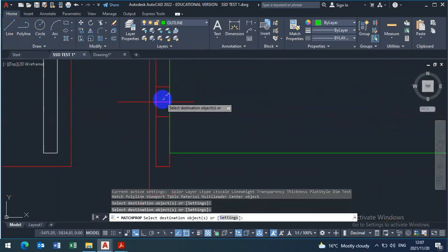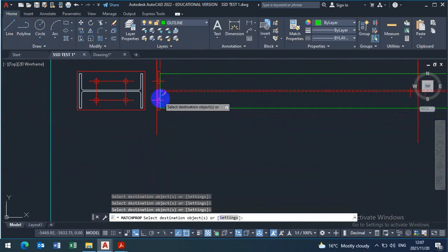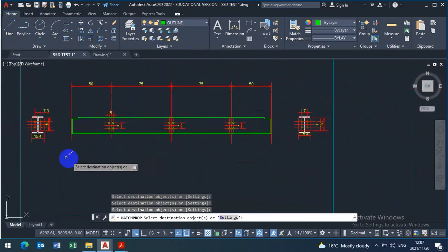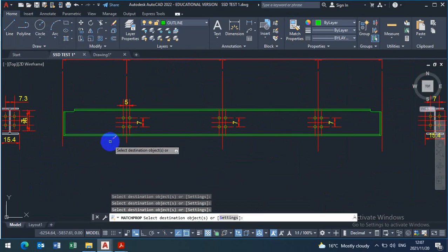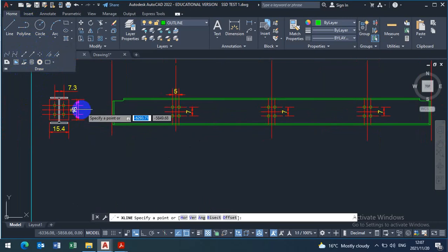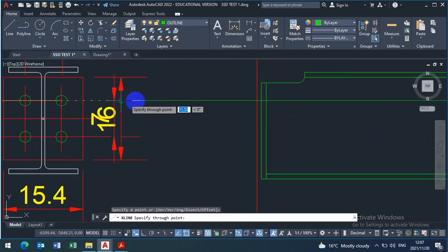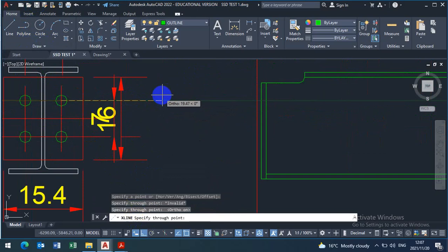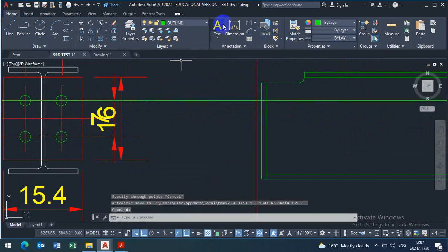These are hidden details, but you won't be able to see the hidden details on this other side. We won't see. There will be holes here which are hidden details, and you need to project center line. Okay, and this should be center line.